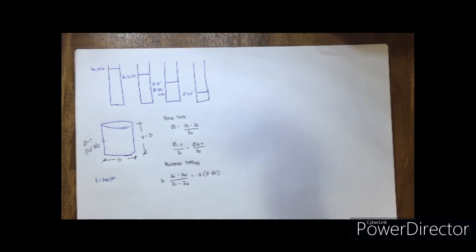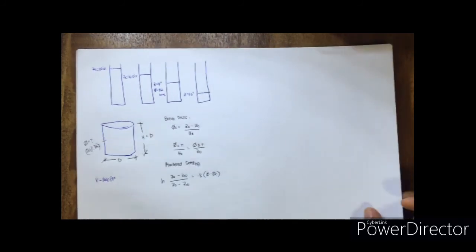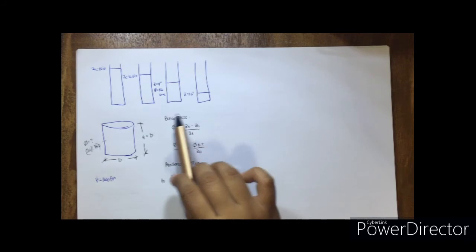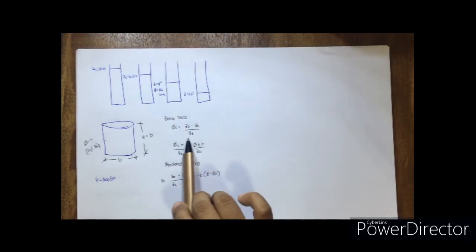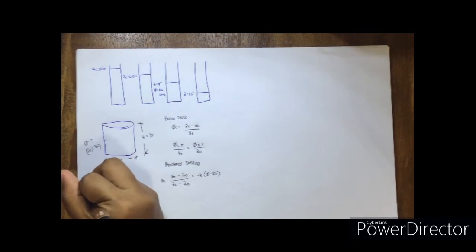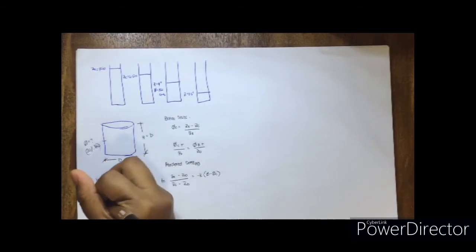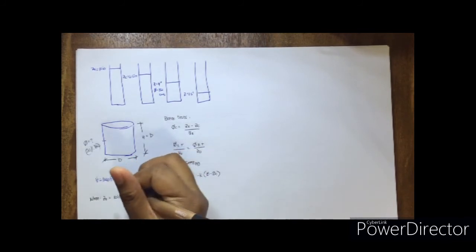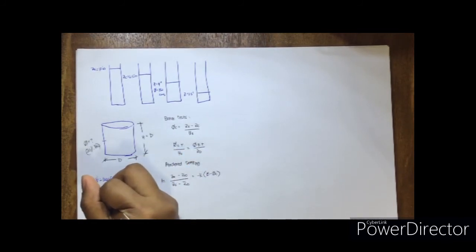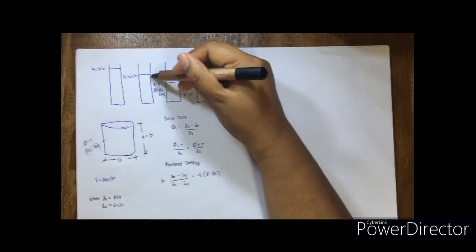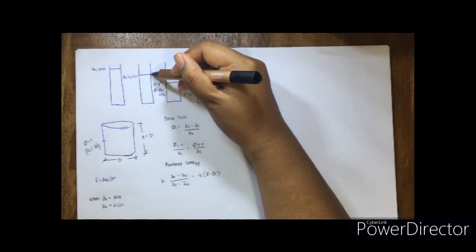Let's start solving our problem. So first, let's take the free settling or the batch test formula. When the original height is 10 inches and before free settling our height is 6.5 inches, so this is the point before the free settling.